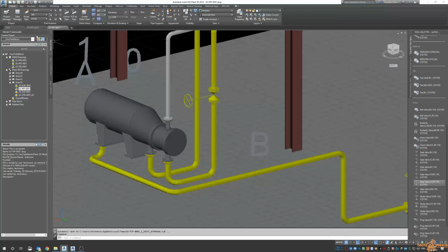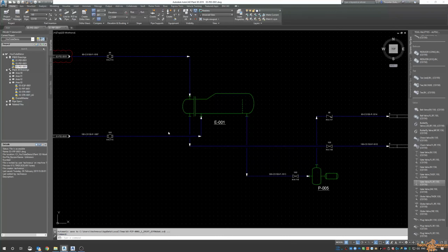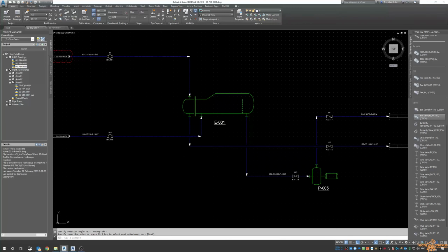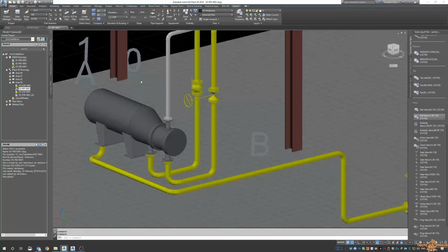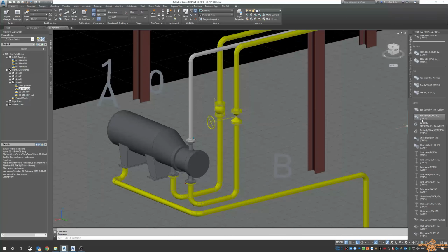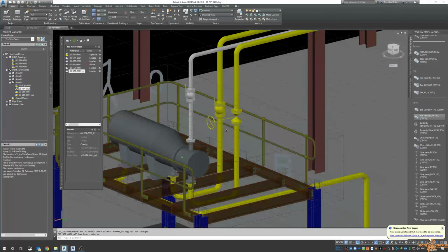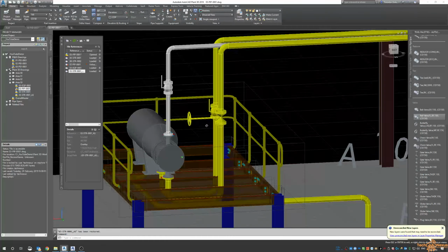So on the inlet of the body, we have a ball valve. So we'll look for the ball valve flanged. And then we have an inlet on the ball valve on the head there as well, which is this line here. So same thing, we can just pick it, orientate it where we want it. So for now it's just an arbitrary position, and then I'm going to reload my structure and then work out where I want to place these.